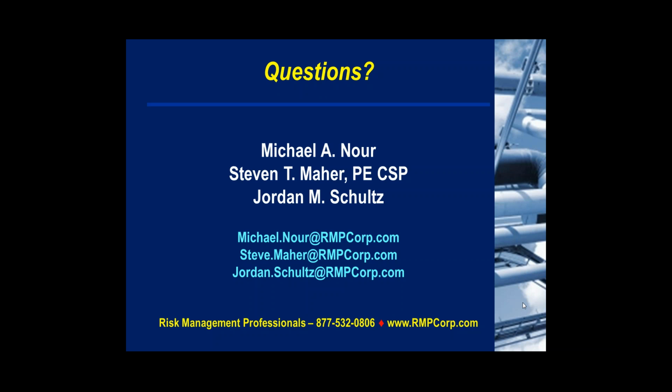If you look at the way a lot of, let me be blunt, a lot of sloppy HAZOP studies were done in the past, they'd put in a whole bunch of items that were basically inherent design features in the safeguards column, and they really didn't help the team sort through the things that needed to come into play during an accident sequence versus things that were inherent in the design. In fact, I've picked up HAZOP studies done by others where they list out safeguards that basically show you that the event can occur.